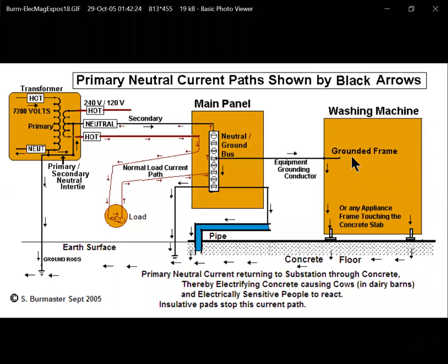That goes out and connects to the metal frame of the dryer. And then here is a pure system ground, because it's going from the grounding system out to a ground. In the electric code, they say this is going out as a grounding electrode. In this particular case, it's a ground rod.